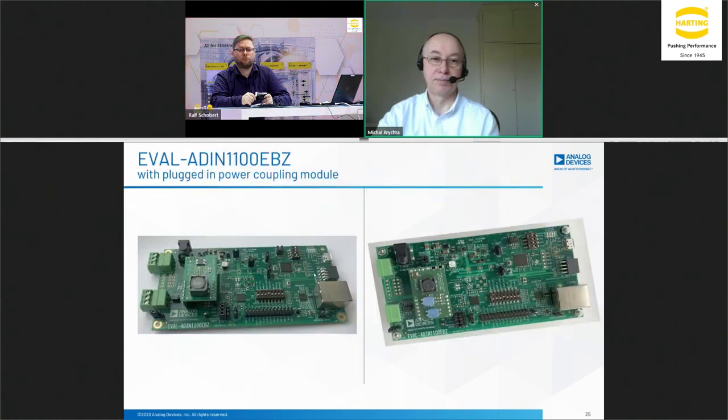We have evaluation boards for the 10BASE-T1L single pair Ethernet. And that evaluation board can take plug-in modules for playing with the power, with the magnetics, specifically with that engineered power. You can see different magnetics from different vendors, and we can combine and play with them. Only power delivery, no common mode inductor or transformer. If you want to start with single pair Ethernet and play with the power at an engineering level, that's the tool that you can have from us. It's available on our web.